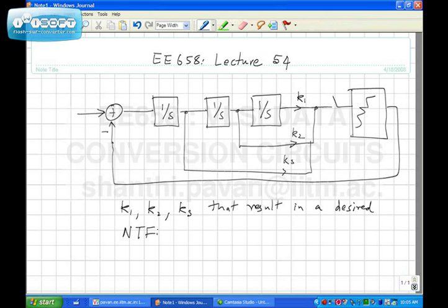about 20-25 bins to make a reasonable assessment of in-band SNR, in which case what you will need is to run simulation for a much longer time, right? So the FFT record length that you take must be a substantial number, which means that the flash converter, which has got a bazillion transistors, must be run for a long time.